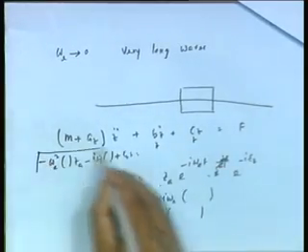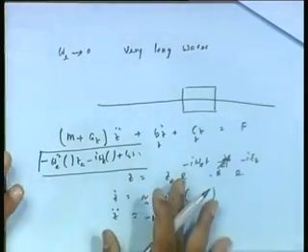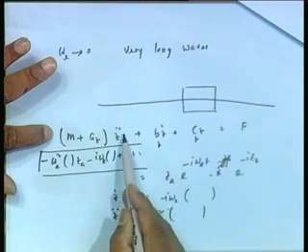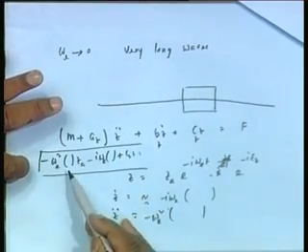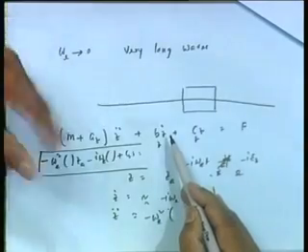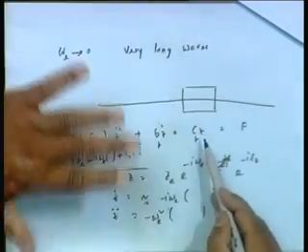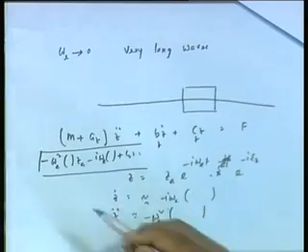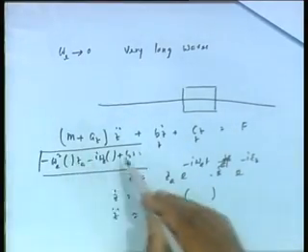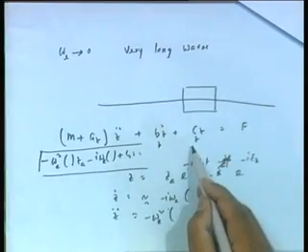Now it will look something like that. Okay, let us pay attention on that. See, the first term, the added mass force, is in proportion to omega e square. Second term, damping, is in proportion, of course forget the phase gap, to omega e. Third one is a constant. Now when omega e tends to 0, this will actually have no influence, very less value, this also will have very less value. So my z becomes simply f by cz, that is what has happened.